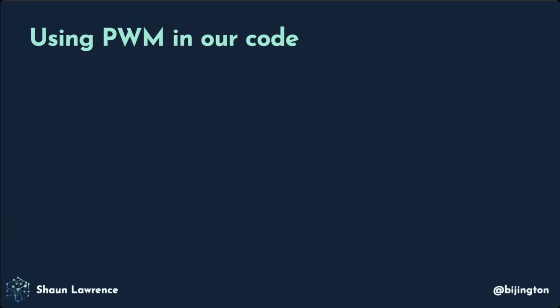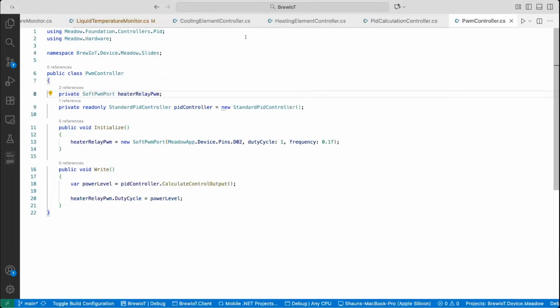So if we then take this into account, what we can do is go and look at some more code. And I don't believe I covered it on the slides, but the Meadow board does support 12 hardware-based PWM ports. However, I always find with any system, if you've got a limitation like that, someone may ask for a 13th or a 14th. So what I've opted to do here is to implement it in code rather than at the hardware level, because that means there are fewer branches. If we did need a 13th or a 14th, you don't have to say, well, if I've reached my limit, use the soft port rather than the hard ports. We can just drive it all through the same code.